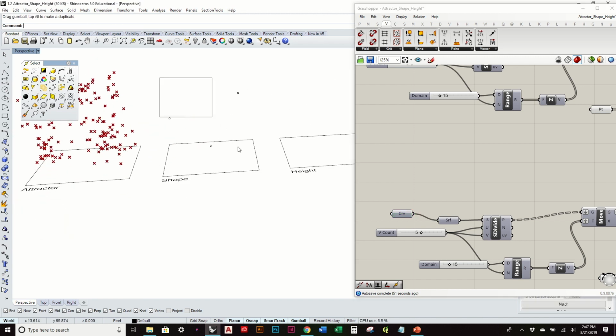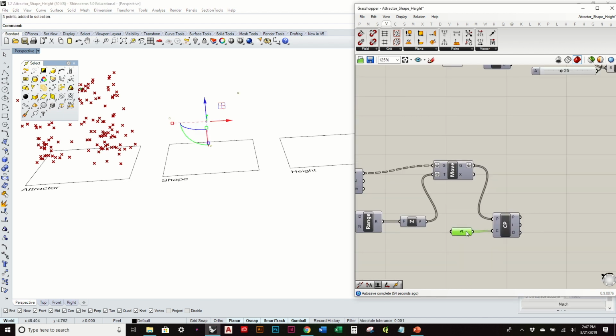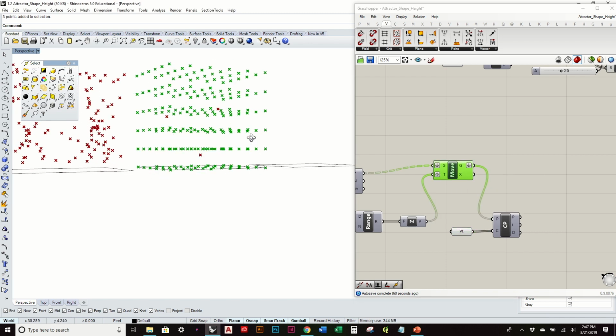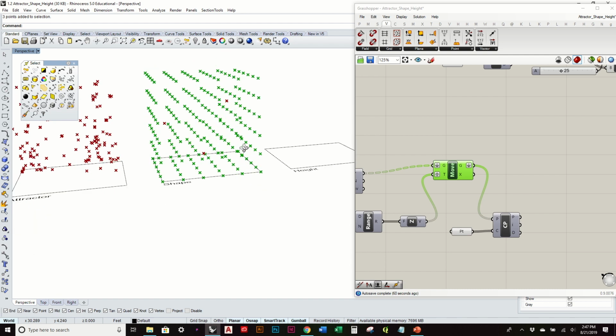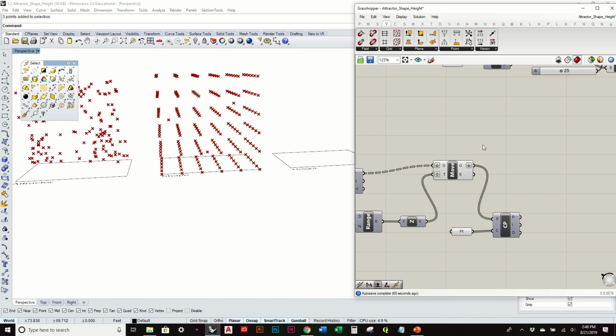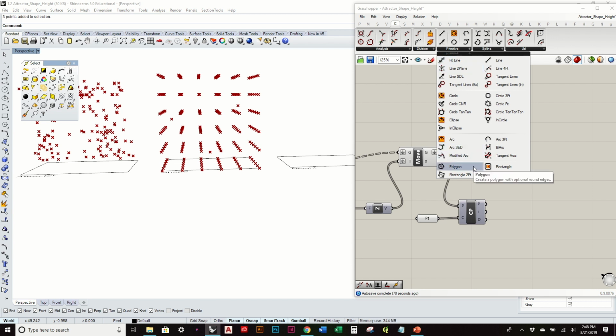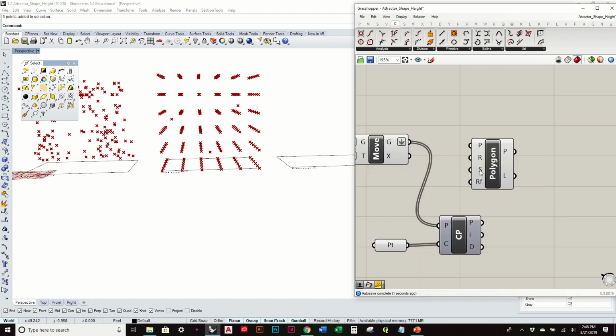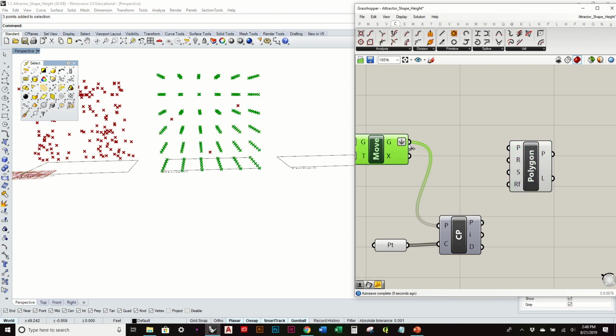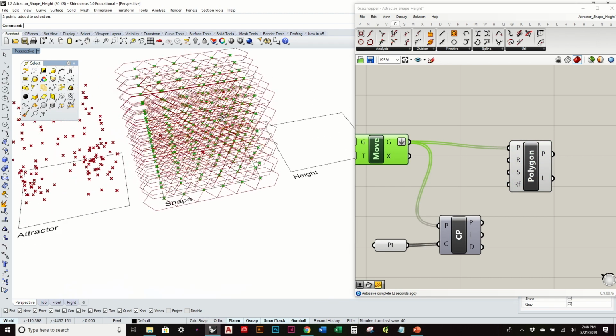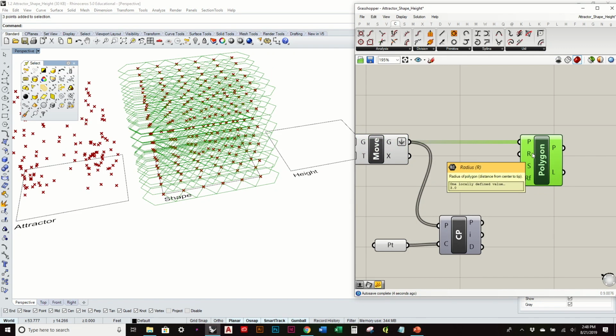Okay. I'm going to use those in here. So again, same thing we've been covering, but now I want to alter the shape of something. So I'm going to go to Curve, Primitive, and like we used before, there's the polygon tool. And why we want to use this is because we can essentially determine, based off the distance, how many segments there are. So we can have up to a dozen or so segments, or we could have it as little as 3 for a triangle.